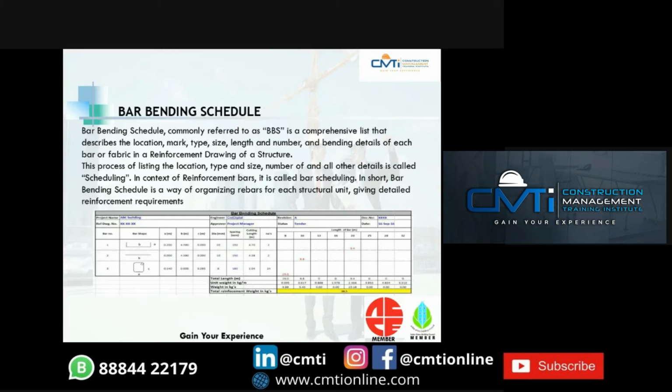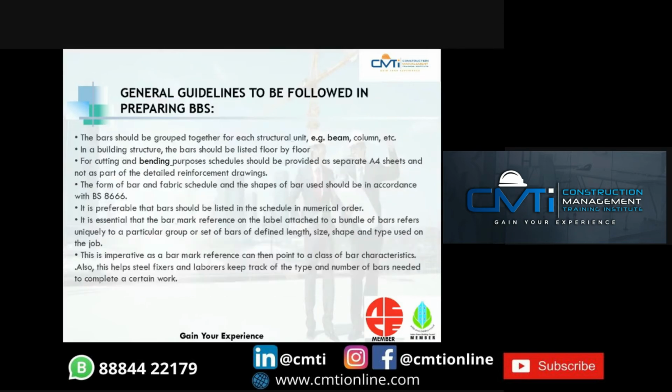the document number, the date, the engineer, and who has approved the project, his name, and what is the total length required, the unit weight, and the total reinforcement weight in kgs. Further, the guidelines to be followed while preparing the BBS.